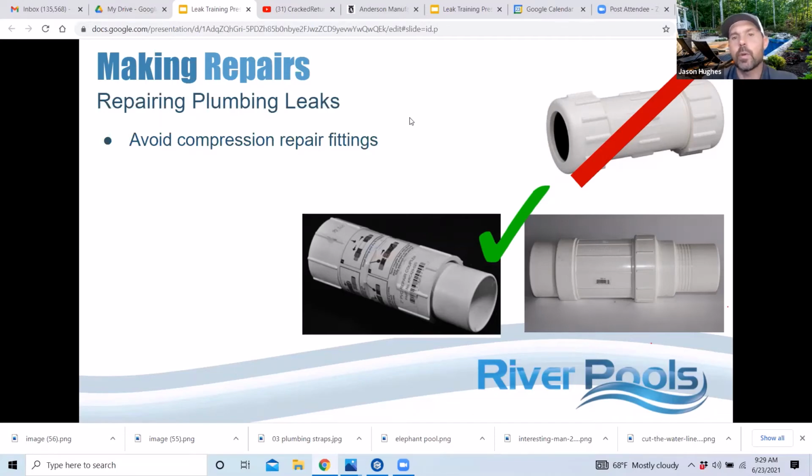There might be times where we even have to 90 up and back over and down again just to make it work, so long as the connections are good and the pipe is secure, meaning if we had to 90 up, we're able to backfill in a way that it doesn't get crushed. Then there's not an issue with that. We do want to avoid using hard 90s on the skimmer lines. We could use sweep 90s or whatever else we need to do there.